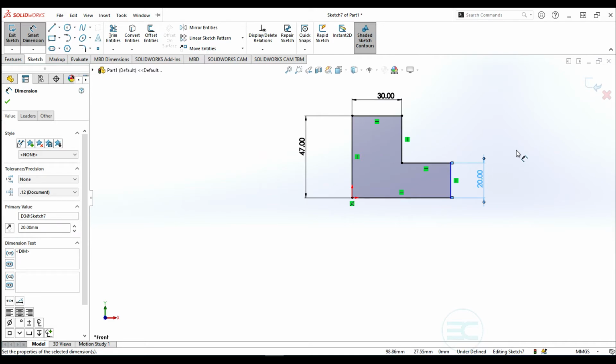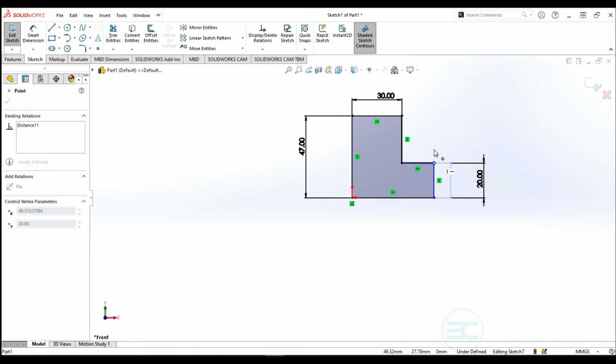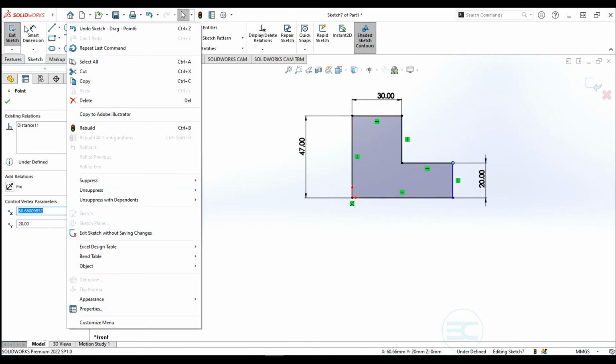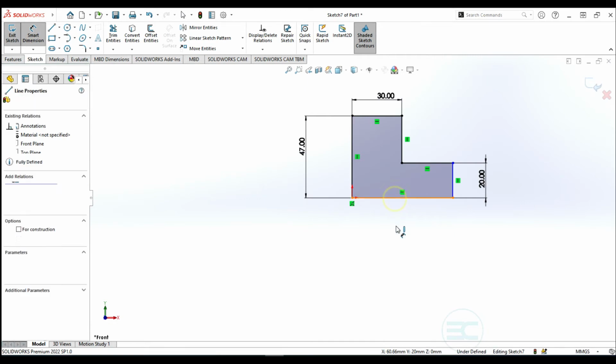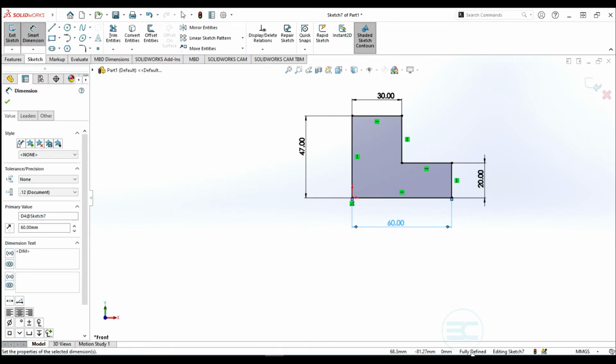Then down here, also when doing dimensioning, you realize you are not sure which part of your sketch, which if you check is showing underdefined, is still missing a dimension. You can just move your sketch or drag it around to see which part is changing. If you check now below the screen, it shows fully defined, and we are good to go.